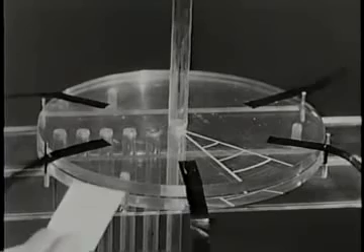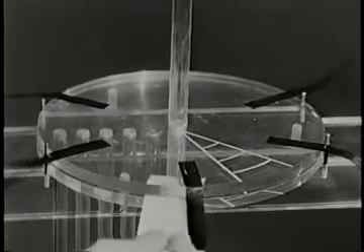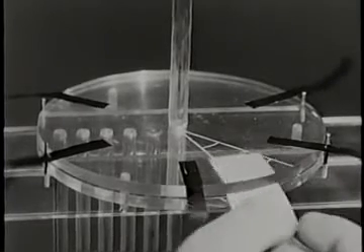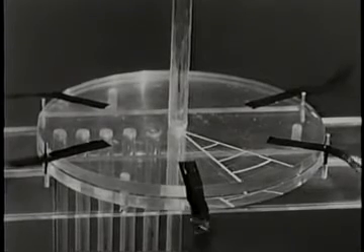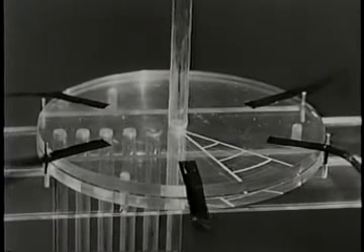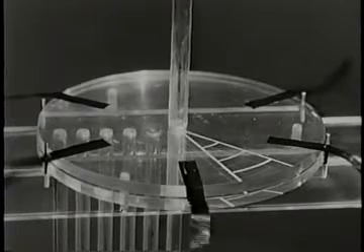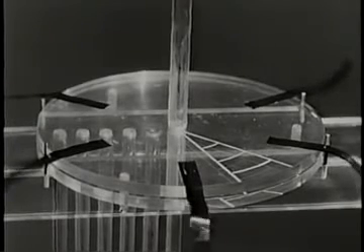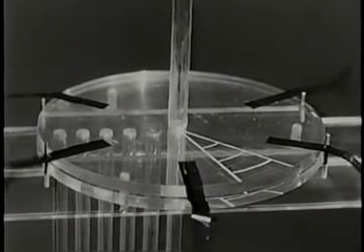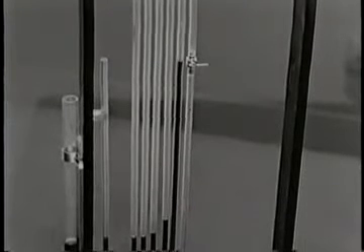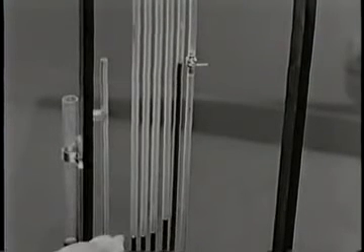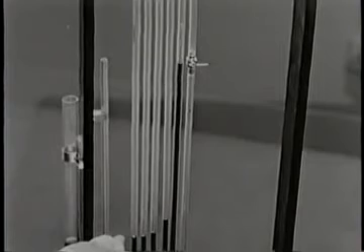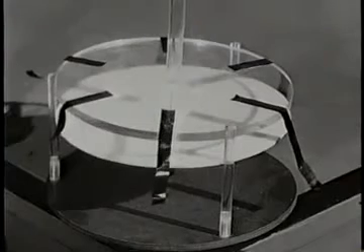Actually, the viscous forces in the narrow gap are by no means negligible. But in this particular experiment, the mass acceleration forces are generally larger than the viscous forces. And so they govern the shape of the pressure distribution. The subatmospheric pressure over most of the area explains why the disk is lifted.